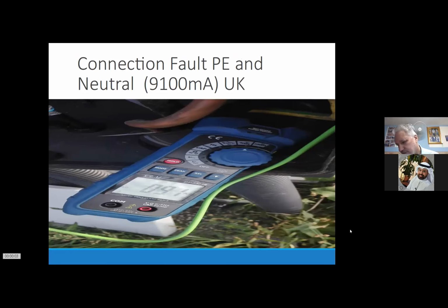Some videos unfortunately don't play, but this is, for example, a connection fault which they made with the second grounding of the inverter. They used a 4-core cable with a yellow-green wire and the typical black, gray, and brown to the PE.